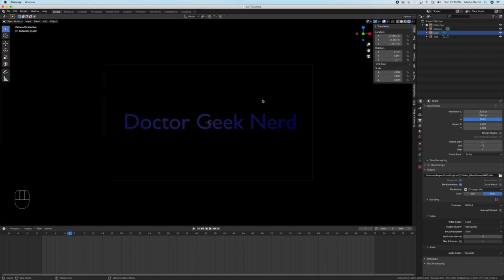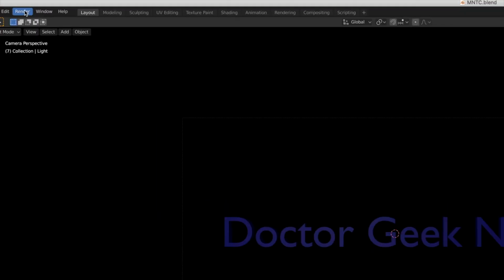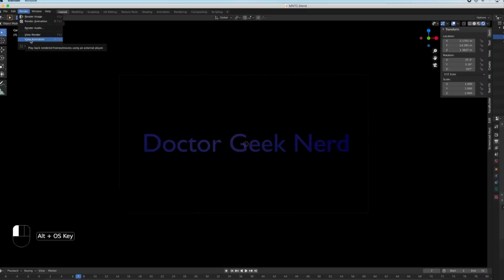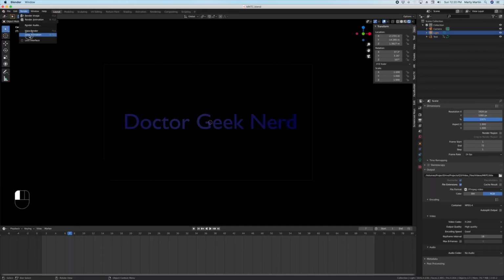Okay, so it's done rendering. I've closed out the last box that showed the last image of the render. I'm going to go up to where it says render again and get that drop down menu, and right here where it says view animation, I'm going to select that.